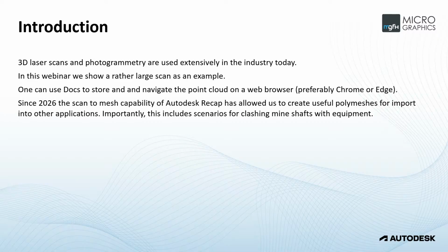So 3D laser scans, they can be very accurate and they can be quite large. They can go up to about 300 meters, submillimetric or millimetric accuracy. And a lot of people use them for reality capturing mines and existing structures, as-built, legacy, whatever information is there, even changing from year to year. I've heard of people scanning foundations from year to year to see if they shift. Even things like roads, rehabilitation workflows, picking up where the potholes are.